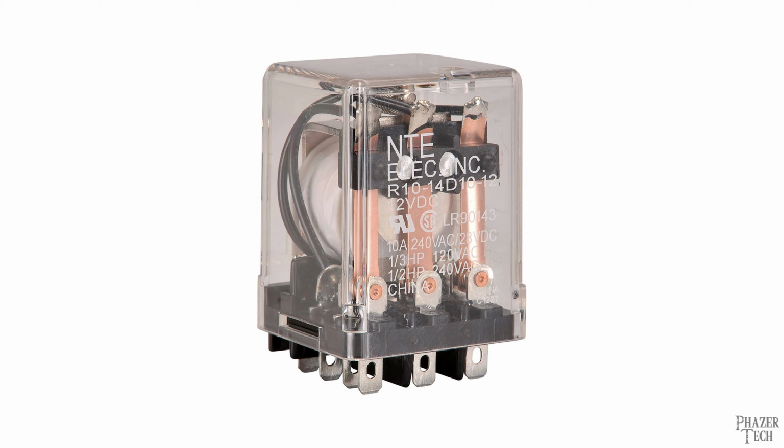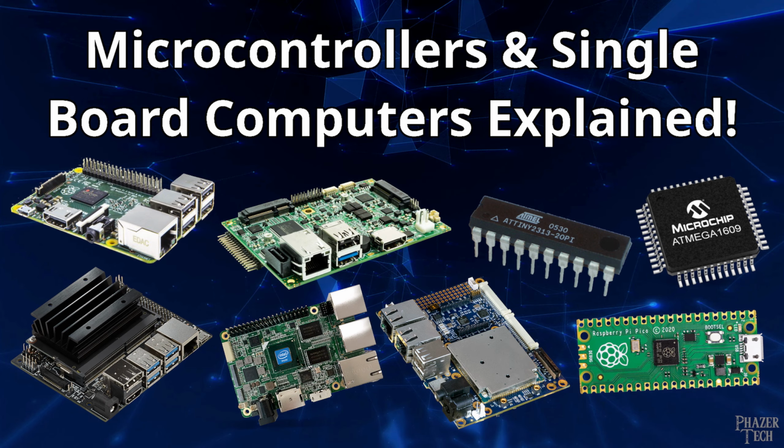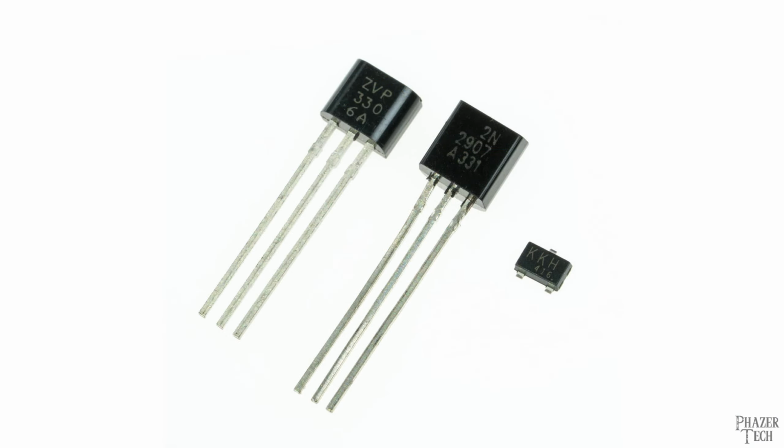Now, like I just mentioned, the advantage of relays compared to regular switches is that we can electronically control them from other devices, including microcontrollers and SBCs. But the output pins on these devices can't supply enough current to activate the coil in a relay, which means we need to use a transistor that can provide enough current. The microcontroller's output pin activates the transistor, and then the transistor activates the relay.